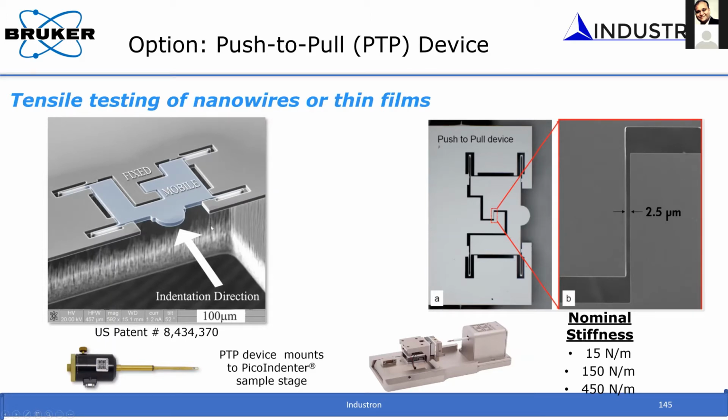For example, if you want to do high bandwidth experiments, you need to go for stiffer springs. If structures are very thick and bigger, you can go for a smaller spring stiffness. For example, nanoscale wires and things like that are very fragile, so even moving the sample from one location to another may break it. In that case, you'd want to transmit only a very small amount of vibration to the sample, so you prefer to use these higher stiffness springs.